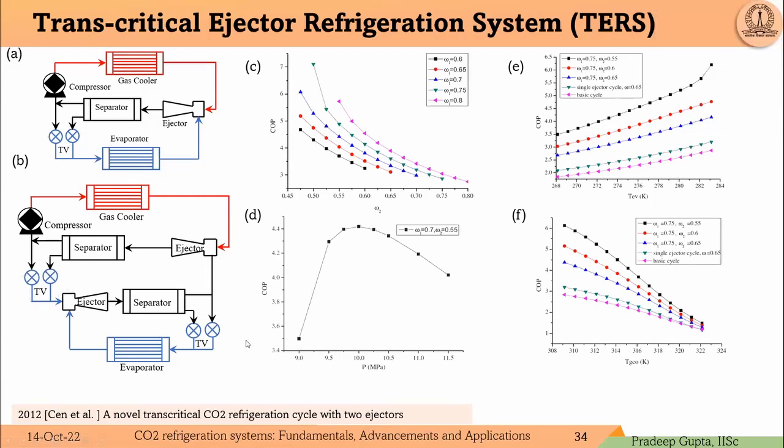See, the first ejector is not recovering fully, because you are not allowing it, because it is not coming down to the lower pressure. You are operating at higher pressure. That is why it is not recovering. You are restricting it from recovering fully.